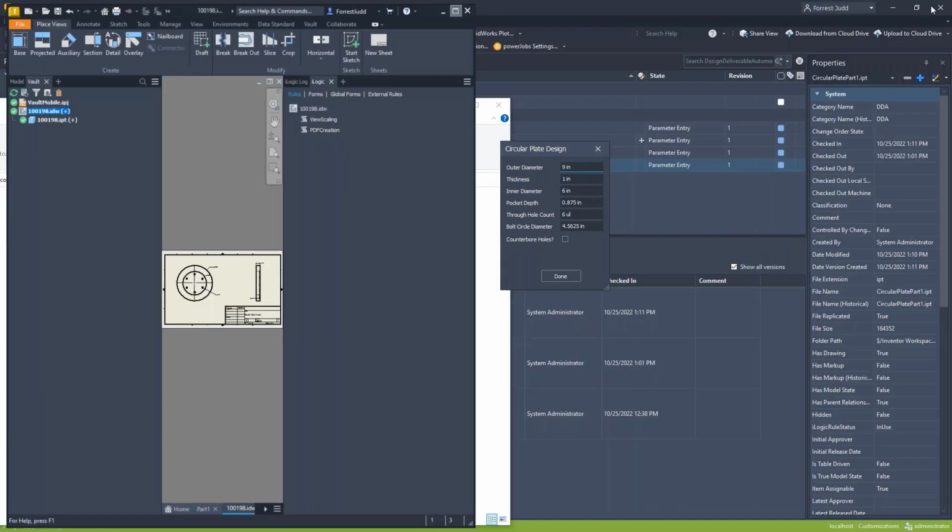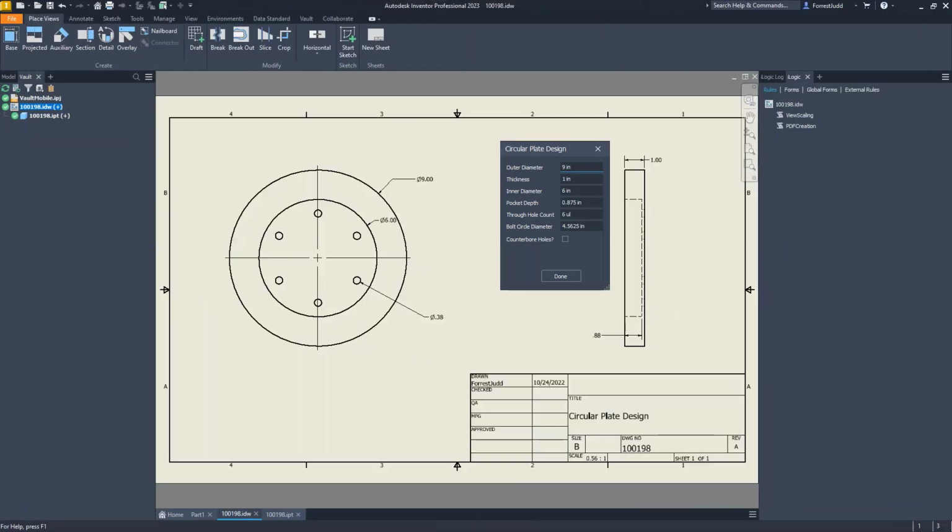Okay, so before we move on, I see another question here. Someone said that I've got VBA macros used for neutral file format creation, so like a PDF or something. Moving from Inventor 2020 to 2022 soon, will users need to install VBA to be able to use them? I believe so. I don't think the default install of Inventor includes VBA. I think it's a separate installation. That's definitely something I would test.